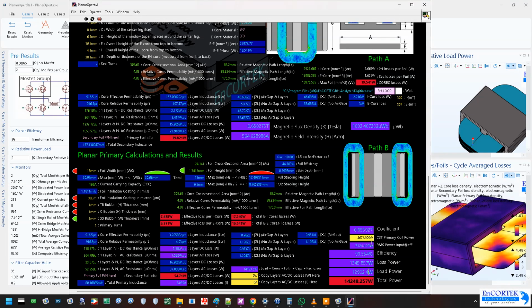If things match up with this and the other platform, when we punch in the other platform's information here, it will compare and we'll know the coefficients. See, closer to 1 is better, right? So you don't try to go below 1 or above 1, you try to keep it at 1. Give or take is fine, but you try to keep it between there, so you know that your calculation for the 3D simulation is accurate.